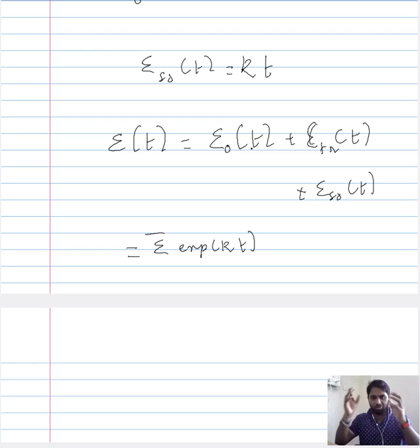and that is the reason why it is referred to as the time independent region. However, when you consider the overall strain, there is an overall strain during this period. It does not mean there is not much strain in this period, but there is a strain in this period, and this strain is expressed by this expression here, wherein there is an exponential increase with time.